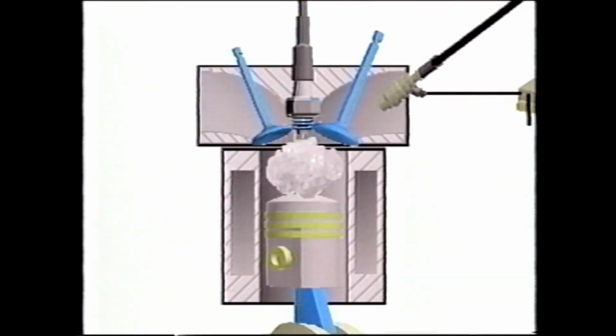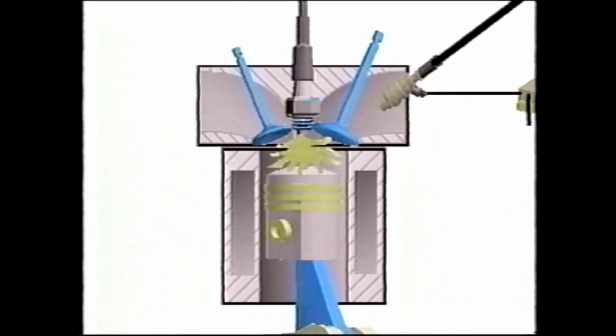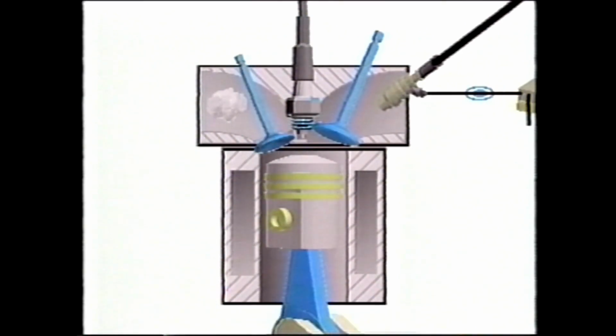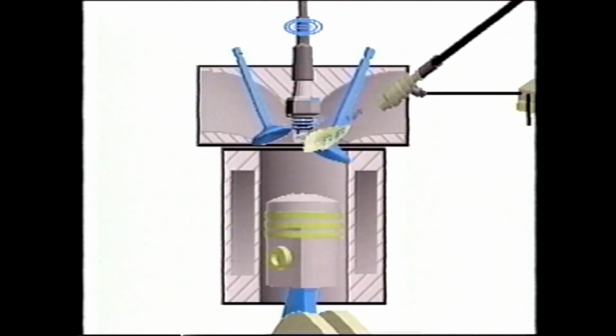Before we talk about the individual test screens, let's review how the cylinders alternately develop negative and positive pressure in the combustion chamber as the pistons move through each stroke of the 4-stroke engine cycle. This will help us understand what the tests are monitoring. Keep in mind that negative pressure is vacuum. On the intake stroke, the piston moves down, increasing space and sucking the air-fuel mixture into the combustion chamber through the open intake valve. Vacuum is created by the downward intake stroke.